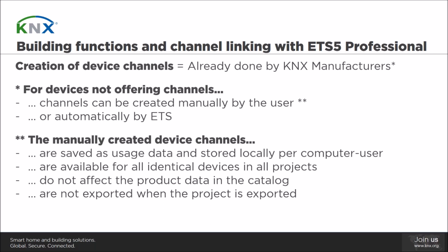Keep in mind that the manually created channels are stored locally in the user profile on the user's computer, and the channel configuration applies for all identical devices in all projects you might have on your computer. And also important, do not affect the product data in the catalog. So the channel configuration is independent from the product data that has been defined by the manufacturer, and that's why it's stored locally as usage data.